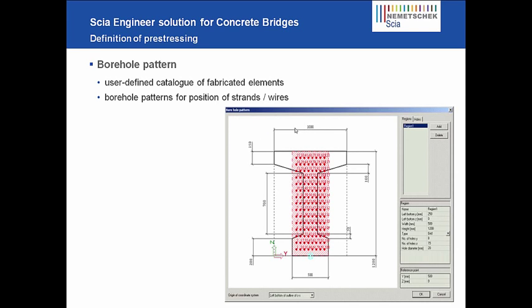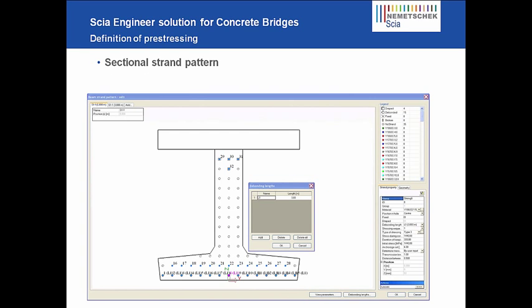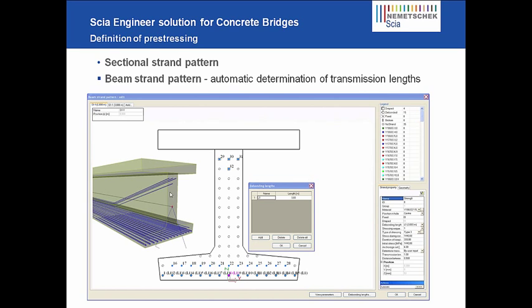And it will be translated into actually this image. What this image indicates is you have to indicate what your stressing bed is. It's actually the steel block where your prefabricated element is created. And then the next step, you will put your wires in it. In Scia Engineer, the result in 3D will be this element, for example. As you can see, it's also possible to create pre-tensioned, prefabricated elements, which have deviated wires, which have deviated tendons.